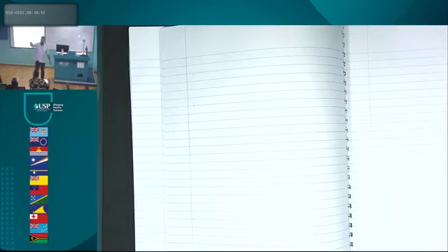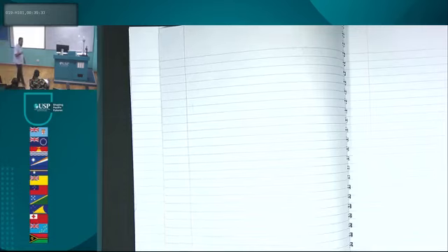Basically, that's just a state diagram going between red, green, and amber, red, green. So it's like a ring counter. It's going in the same direction, but the difference is in the timing, the difference is in the clocks. So you've got to build clocks to do the counting.